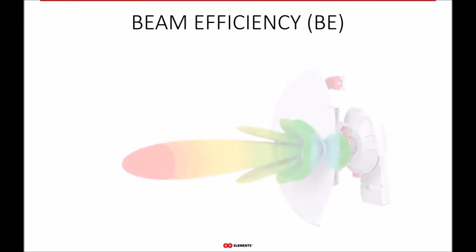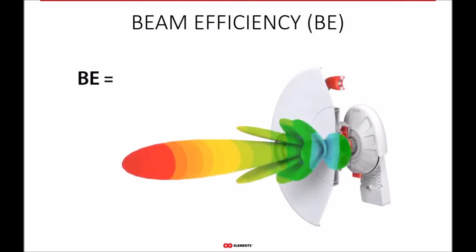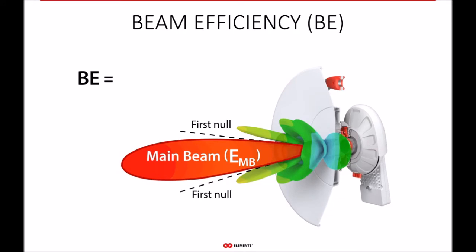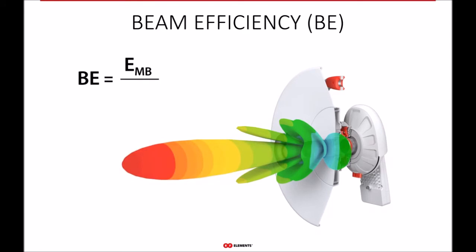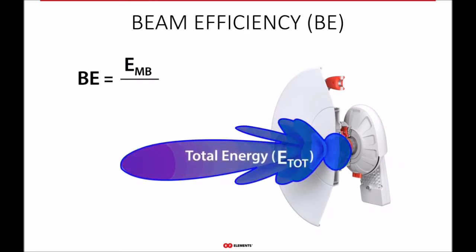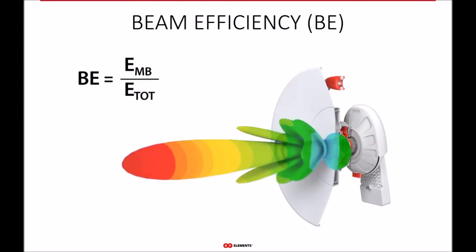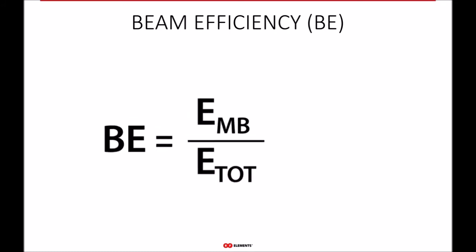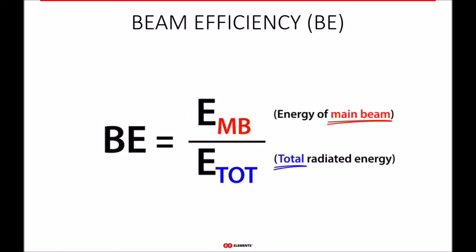So the higher the beam efficiency is, the more energy is in the main lobe, in other words, where we want it to be, and less everywhere else, meaning in the side lobes. So beam efficiency quantifies the side lobes. It gives us a numerical value that very clearly says how many side lobes an antenna has. So comparing any antennas in terms of side lobe performance is extremely easy. The higher the beam efficiency of an antenna, the fewer side lobes it has, period. As simple as that.